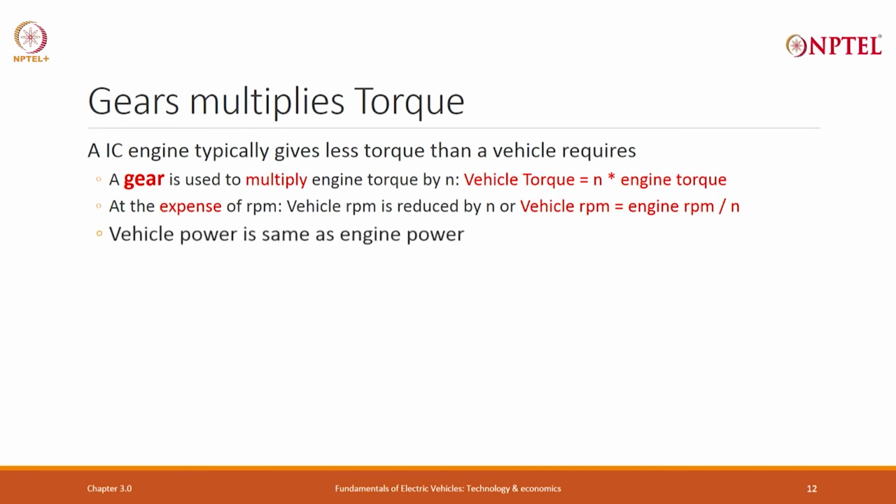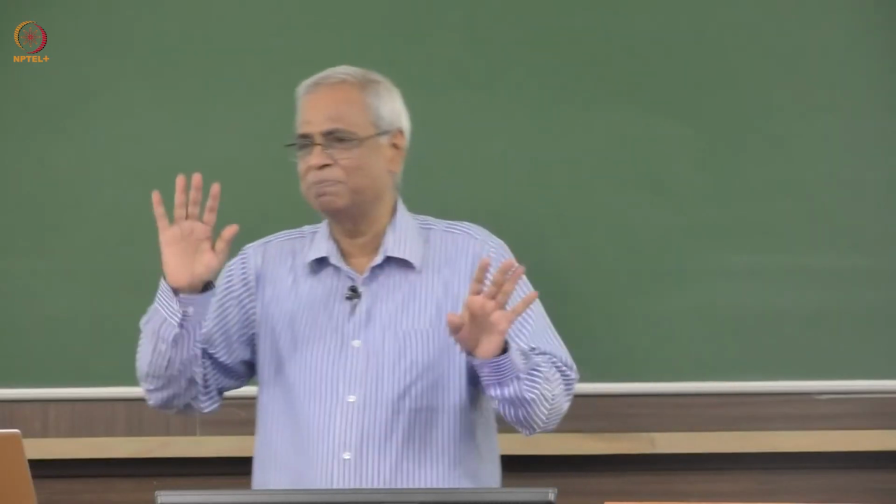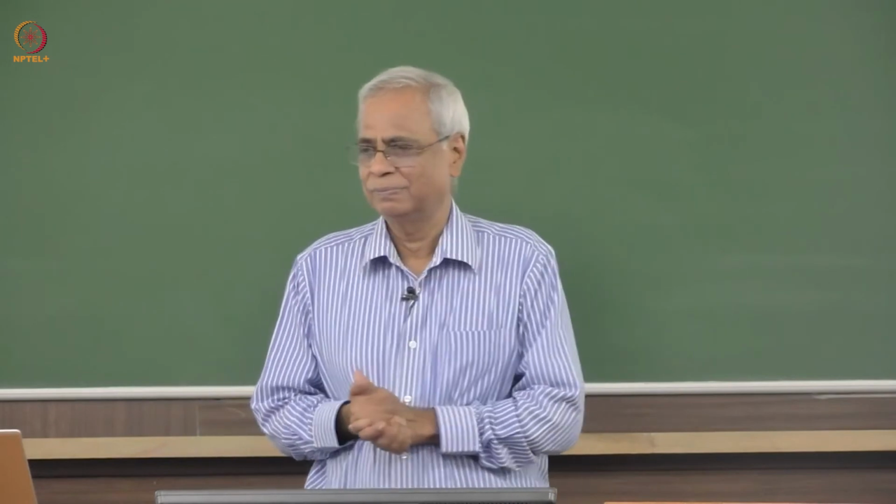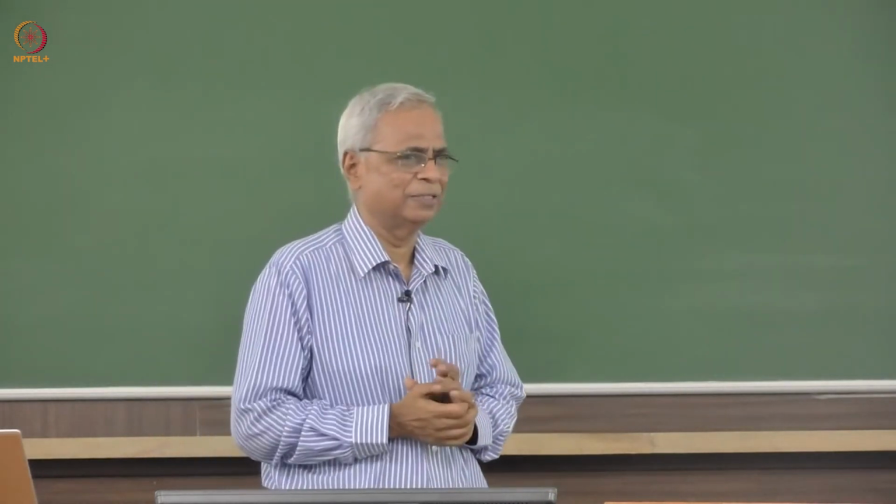Vehicle power is engine power. So, there is no difference between vehicle power and engine power. Torque gets multiplied, rpm gets reduced by the same factor. So, the vehicle power and engine power is the same. You will see the same thing in electric vehicle.